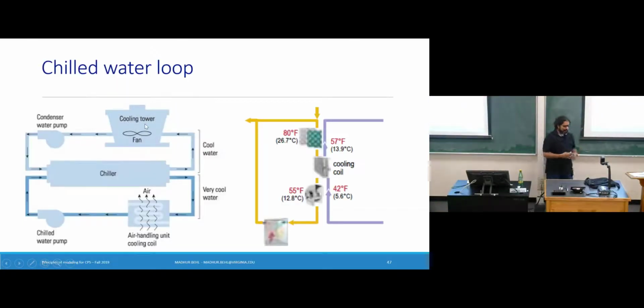In a cooling tower, you have water at a high temperature. A fan is blowing the water down into a pool, and in doing so, it's breaking the water into very, very minute droplets, almost like a mist. And when this mist falls a certain height, it eventually rejects the heat to the outside air.